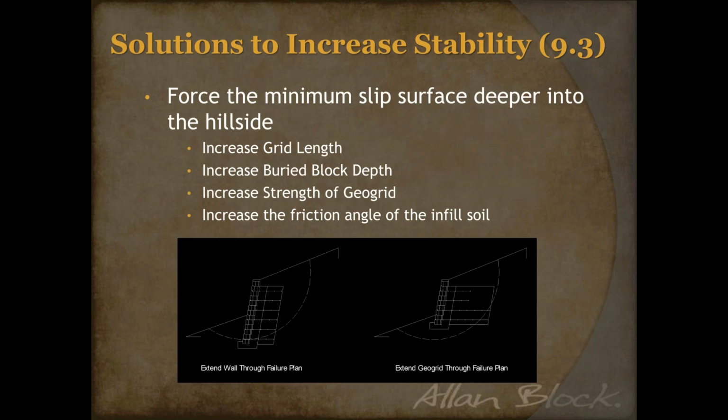All right. So you've run an analysis and you found out that your global stability safety factor is below the minimum. What is the minimum? I do believe the minimum for global stability for static situations is 1.3. I've also heard people say it's 1.5 or 1 or 2. That all depends on your comfortability. I do believe, though, the absolute minimum is 1.3.